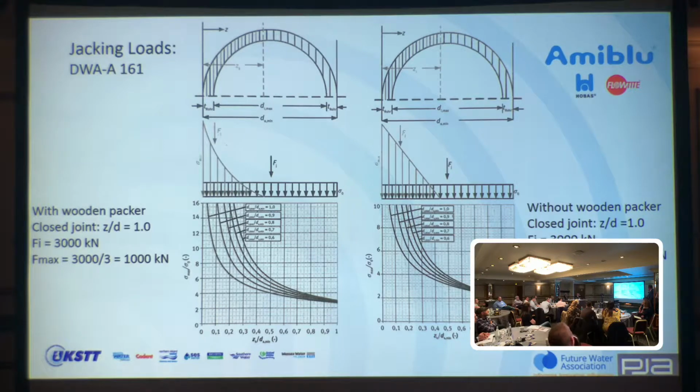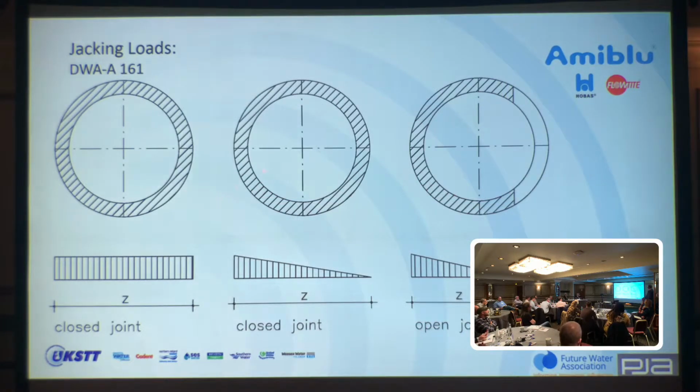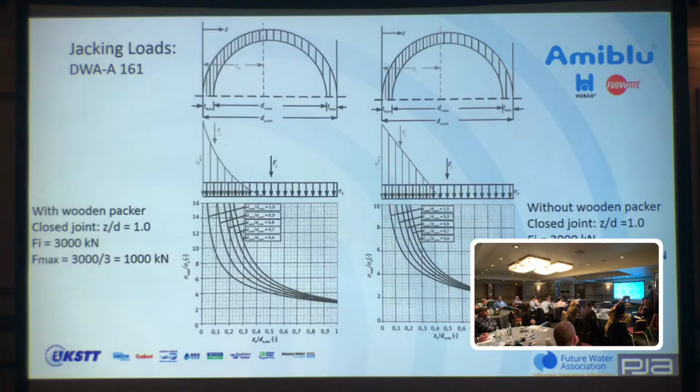when we look at the German guideline, what does it say at this moment about jacking loads? If we have a closed situation, in this situation, just closed, if you use a wooden packer, then you have to divide your jacking loads by 3.